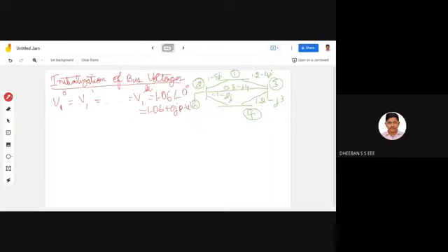So now coming to the second bus. As per your question, it is a PV bus. Also, they have given you the voltage, so you have to consider that voltage as the initial value. Your V2 not, you have to consider the voltage value which has been given. So it will be 1.04 + 0j per unit. In brackets you can just put it as the generator bus.